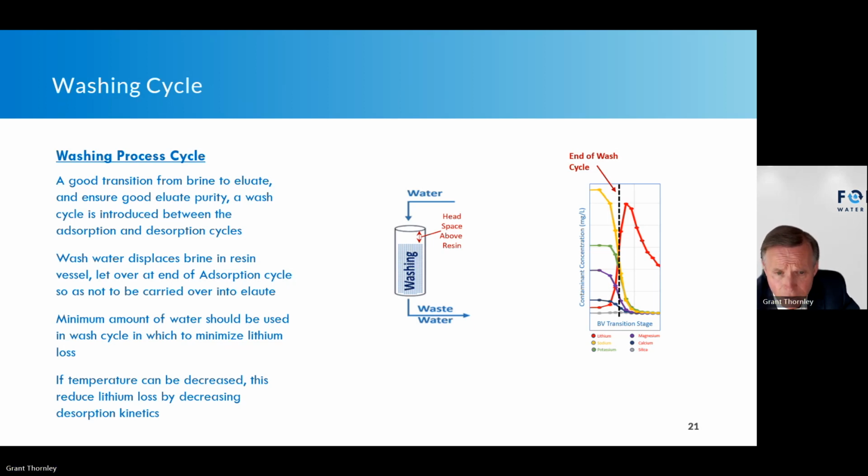The other aspect of washing is that, remember we talked about temperature increases the kinetics. Well, if I decrease the temperature in my wash water, that will actually help me minimize lithium loss during that process cycle.